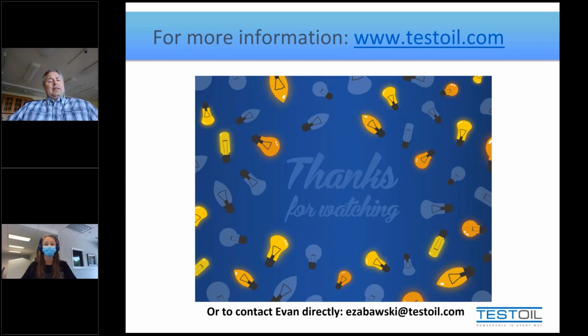If there's anything more detailed than that, like where on a compressor you might want to sample it, we could always answer that question via email. But generally speaking, most people take it from where the oil separator is located or just upstream of the filters, which are two easy to access points. So you can either add a valve, or sometimes on some brands, there is already a sample valve located there.